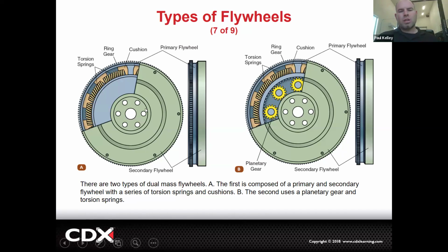They'll sometimes call this a torsional damper. The reason they call it a torsional damper is because remember, your engine, which is in the center, your crankshaft's right here, it's getting those power pulses. Cylinder 1, 2, 3, 4, boom, boom, boom, boom. Those pulses could actually make this thing go fast, slow, fast, slow, fast, slow. The pulses are going to be punching the inside of this thing.